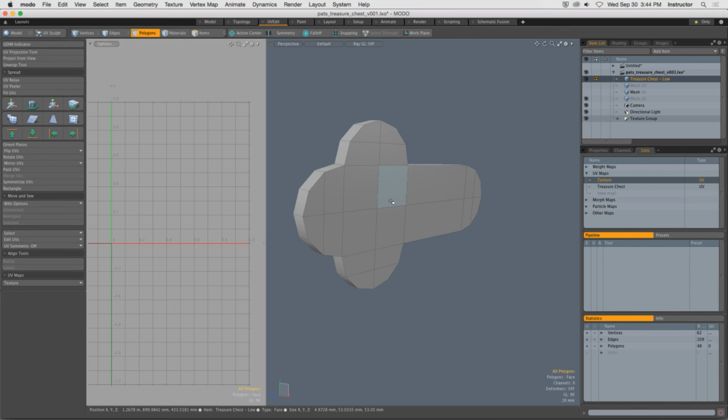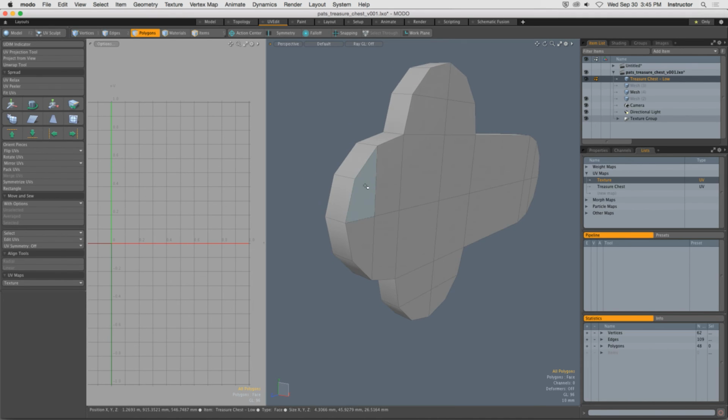Select the seams and use the UV peeler or the unwrap tool. Unwrap tool is definitely the one that I would use. Now, which edges would we select? The ones going around it, right? Kind of, yes, absolutely. Imagine this is a cardboard cereal box, okay? And you need to flatten this cardboard cereal box out, okay? Which edges would you select? The corners going around all these radiuses, okay? Which happens to be almost every single edge in this bit here, okay?